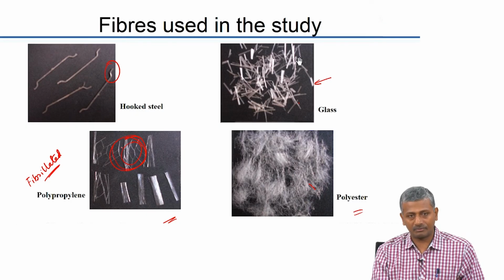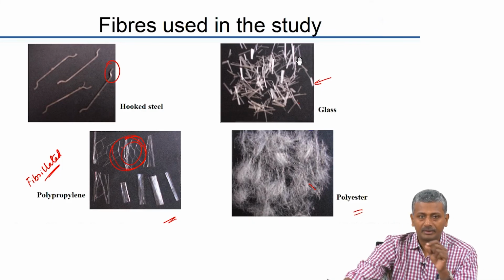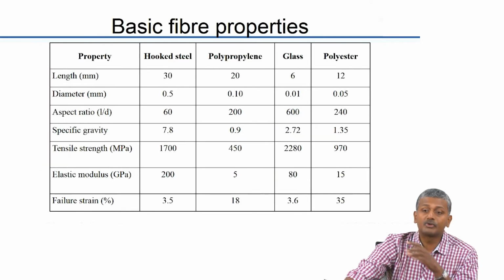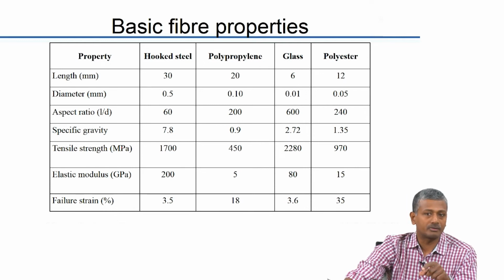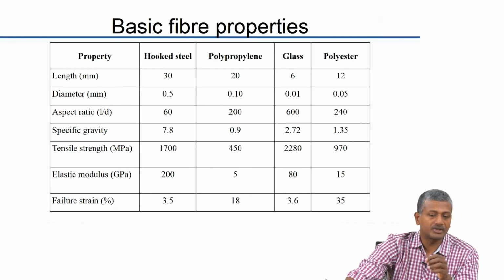So, fresh concrete is wet. If you have a hydrophilic surface, it gives a much better bond with the concrete system. So, fiber properties can be modified by surface treatment to give you a much better bond. Now, of course, glass fibers have to be treated first to ensure that they do not interact with the alkalis in your concrete system. So, these are mostly treated glass fibers, because otherwise they will create a problem sitting in your concrete.